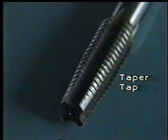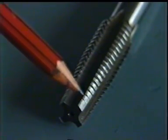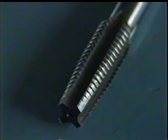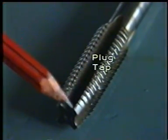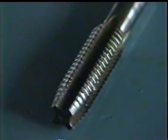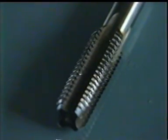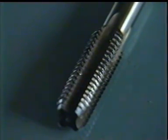In a taper tap, 8 to 10 cutting edges of the tap are tapered to facilitate easy start of the operation. Whereas in a plug tap, 3 to 5 cutting edges of the tap are tapered. In case of a blind hole, bottoming tap is used after the plug tap to finish the threads up to the required length. No taper is provided on the cutting edges in this case.